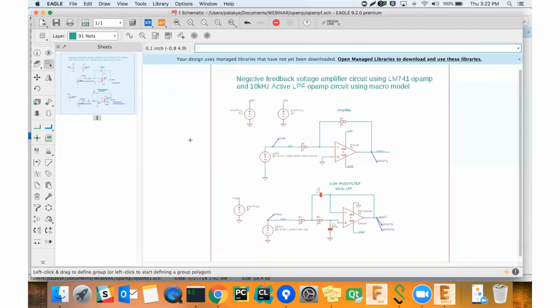We also took a schematic called Convert, which ships with Eagle, and we converted that circuit to be simulation ready using the add model command and the related interface and dialogues. And that's an example of how you take any schematic, your schematic for your new great hardware device, and convert it so that it's simulatable.